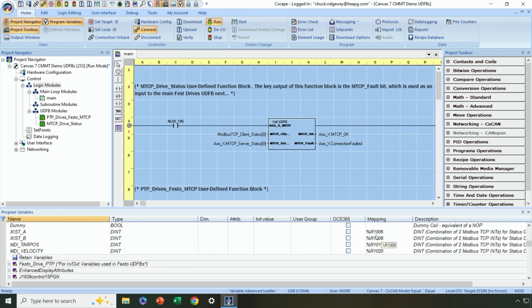So that's really what that's all about. Again, if I would have tried to place a double integer data field on a screen that was really 2 single integer values concatenated together, I would get a type error. Okay, it wouldn't work. So by creating this new variable that's truly double integer, that's mapped to the same location where those 2 integers are located on the Modbus side of things, then boom, it works just fine. Okay, I just wanted to cover that with you briefly.